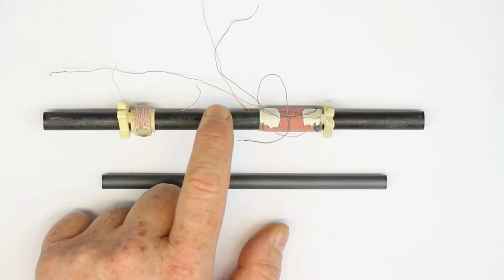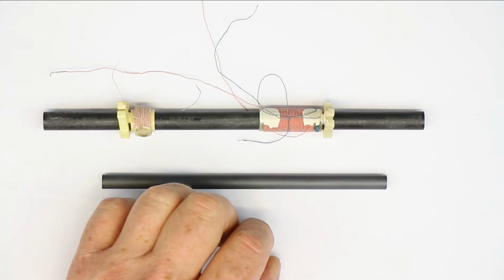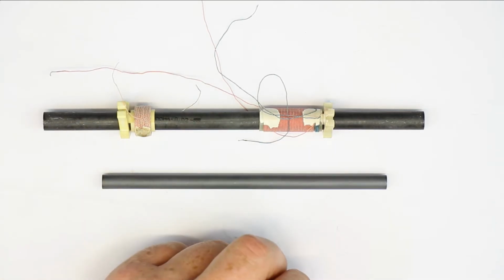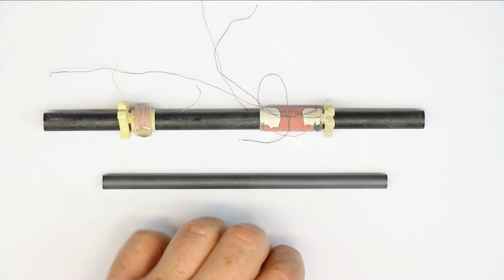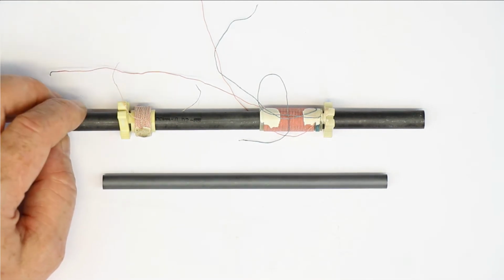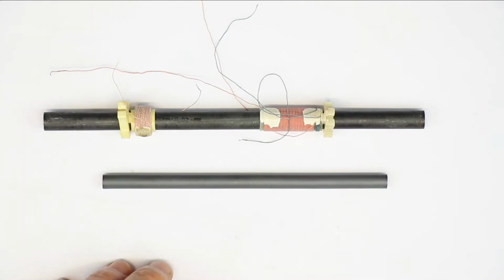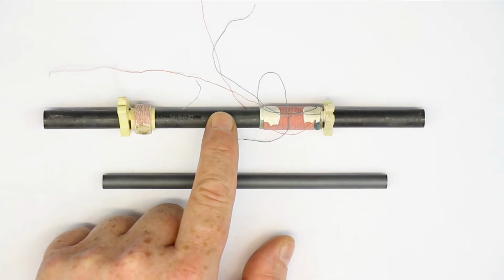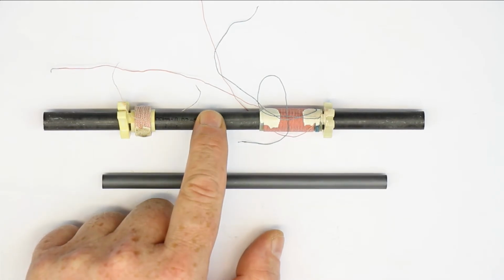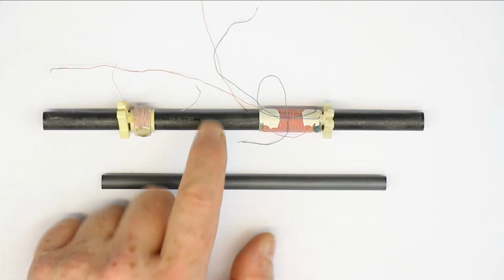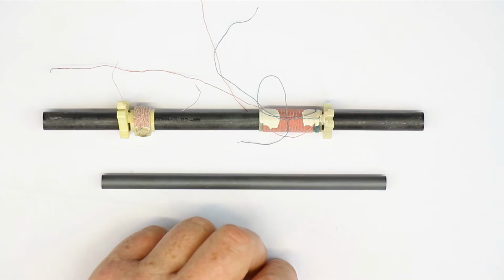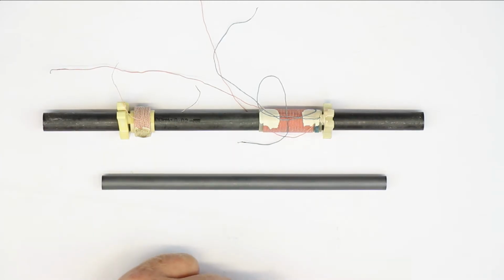A standard Litz wire is not usable for frequencies above 1 megahertz, which means if you want to go into the shortwave range, you cannot use Litz wire anymore. You can, of course, but the quality factor of your antenna will drastically go down. And the second is we have to watch out what kind of ferrite material we use, because not all Ferrite-Rod materials are suitable for frequencies above 1 megahertz.